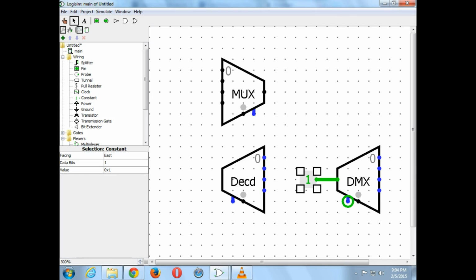That's because with the select bits, one of them would have to be selected. That's why we have to have the deselect on, because one of the outputs has to be connected to the input. But if I'm not ready to update any one of the 4 registers, I don't want any one of them to be selected. So that's why I need the enable pin to turn off and say, okay, none of you should pay attention because I'm not changing any one of the 4 registers.